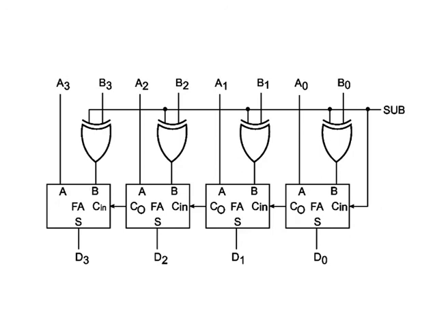The output of the full adder in this case gives the result of subtraction of the two numbers. The arrangement shown achieves A minus B, the final carry, that is, the carry out of the MSB full adder, is ignored if it is not displayed.